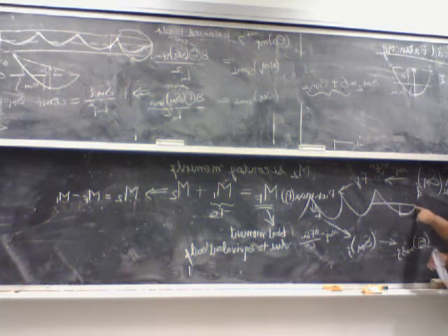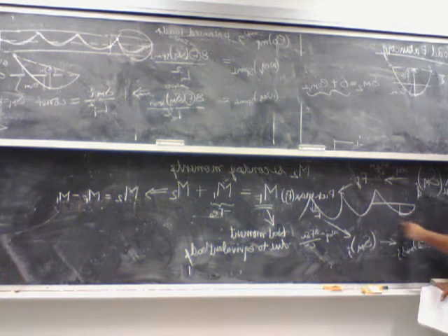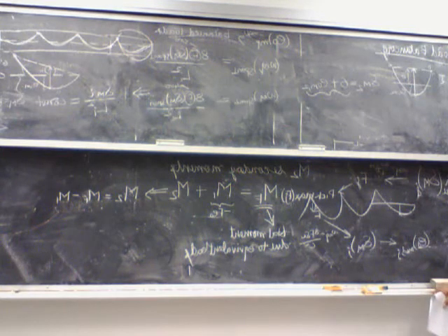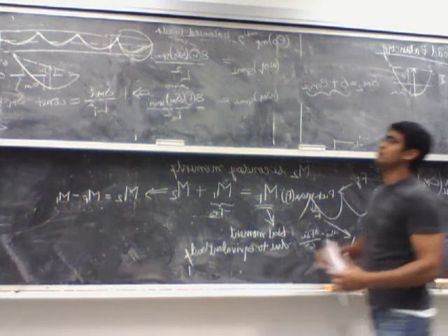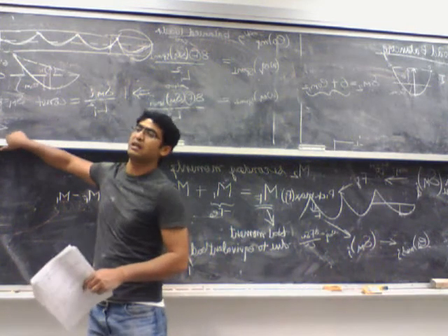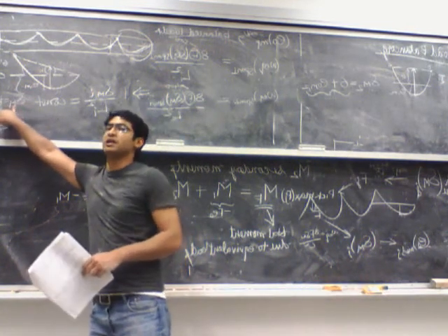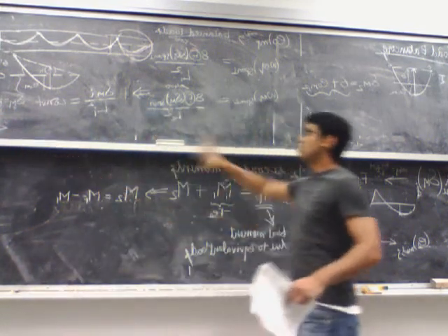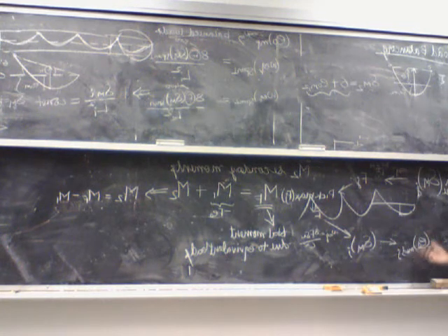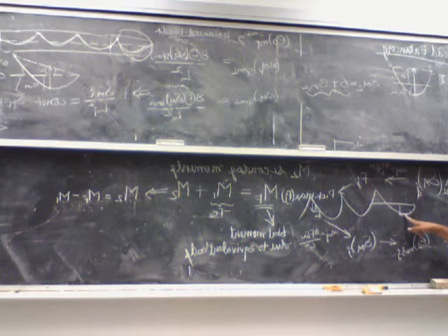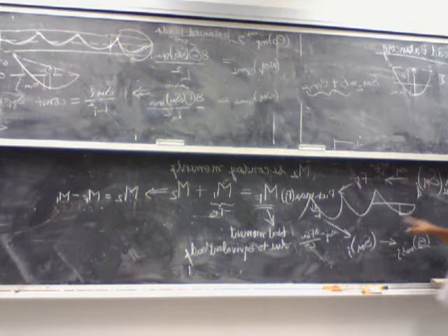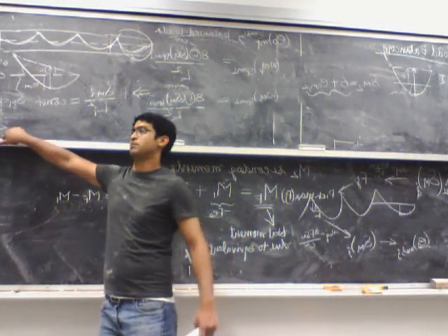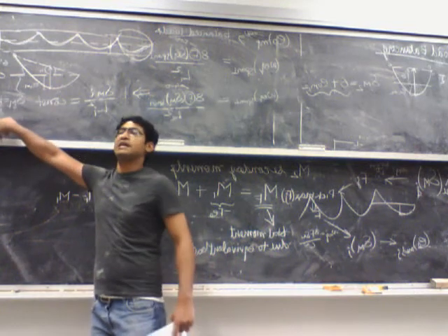So you still need to go ahead and make sure that the maximum E naught anywhere is still less than E naught MP. If that doesn't happen, you need to decrease this factor a little bit further. So let's say you started with 90% here, so you said it's 0.9 times E naught MP. You do all these calculations, you come back and you see that if you pick 90% at the mid span, this actually becomes more than E naught MP by 1% or 2% or 5%, doesn't matter. That means this 90% is too big a number. So you decrease it to, let's say, 85%.